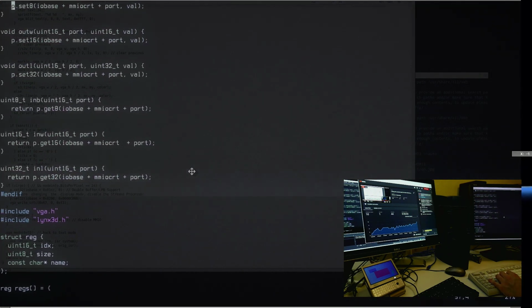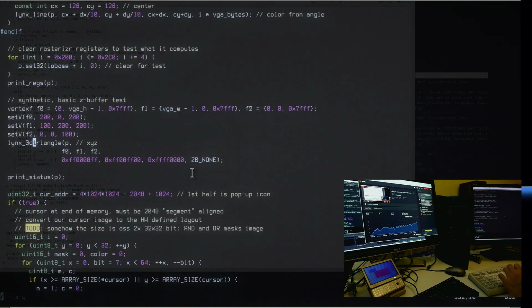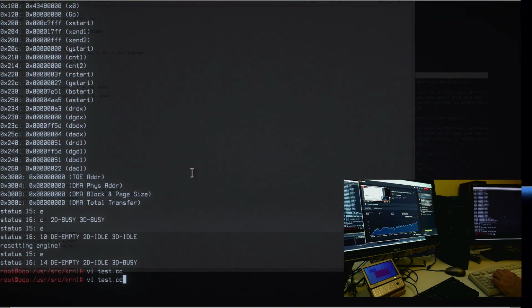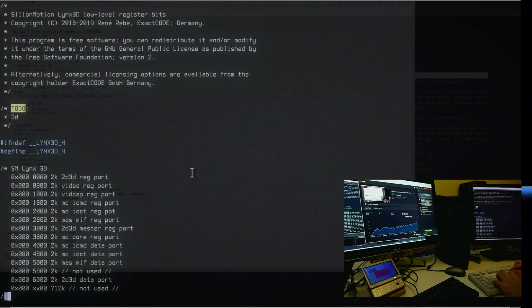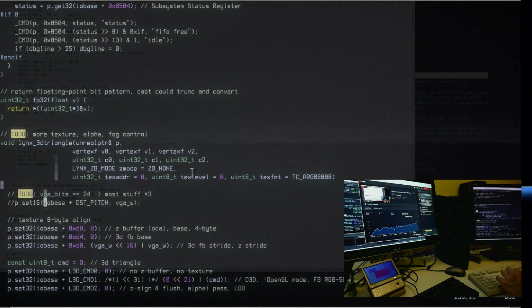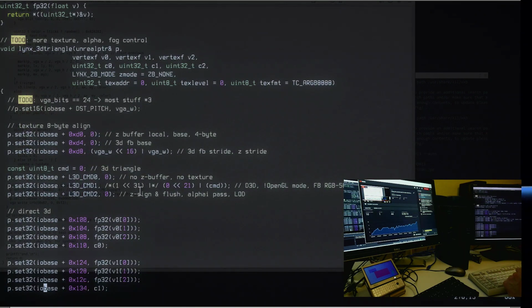For texturing, it is, by the way, not so much needed, triangle here. If you wanted to do texturing, which file did I even open here? No, it's not the right file. So to enable texturing, you go here to triangle and you just enable a couple more bits. So this would be in the command register somewhere. Well, first I would suggest not to do this with set buffering. Set buffering is here also, no set buffering, no texture. So enabling texturing is just setting some texturing bit, loading here some texturing base address wherever that was.